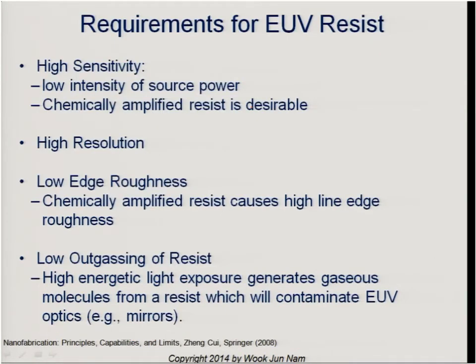Still, the light source of the EUV technology is not stable. People are using a pulsed laser or laser-based plasma or just a plasma to make this short wavelength light. And then the intensity of the light is not high enough. And then we also lose light through the optical systems.